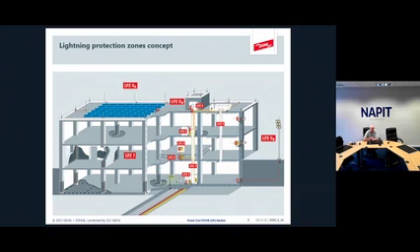And what you can see is that what we're looking at is any cable. So there's PV on the roof, that comes from the outside in, they'll have SPDs. The satellite dish on the roof, that can have an SPD. The CCTV, external lighting or the barrier entry system, anything like that, where it could bring a surge from the outside into the installation, there's going to be SPDs there.